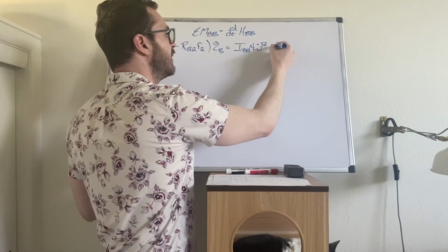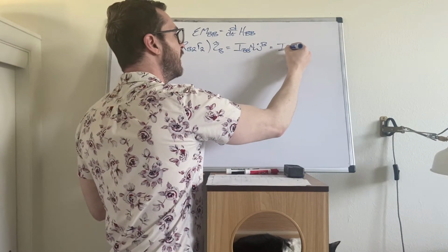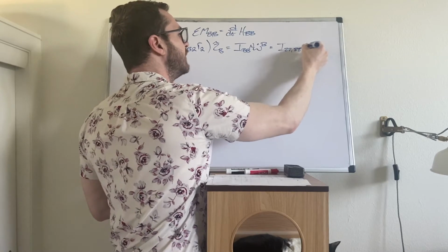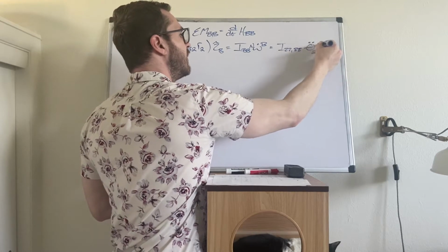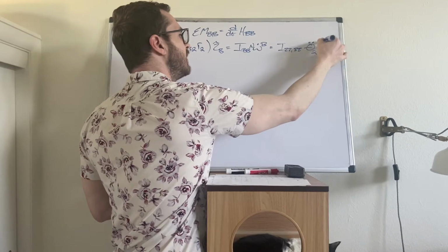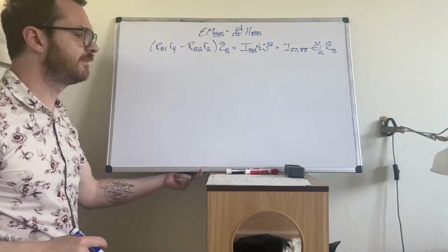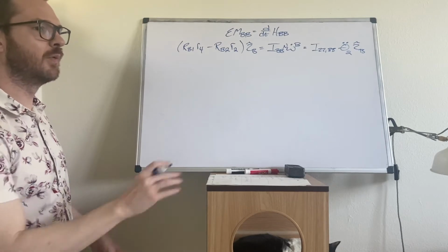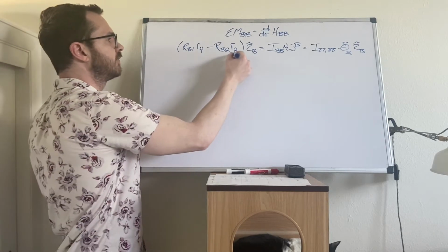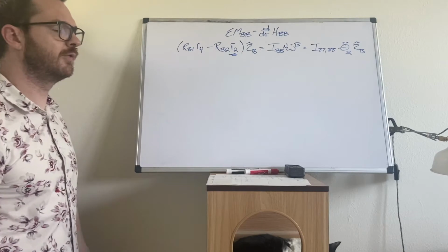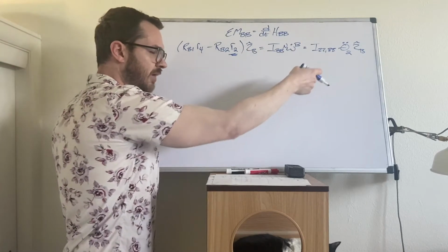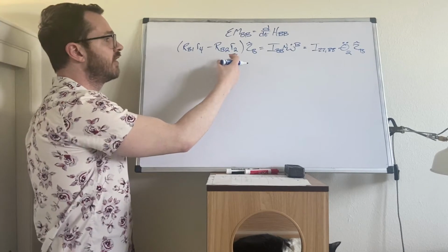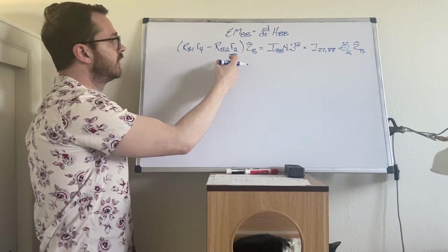So I_B, omega, and B. And the same assumptions that we did on body A lead us to I_ZZ,B and theta 2 double dot, and this is about the ZB axis. Okay, what was the point of us coming here? We wanted an expression for R2. Well, we can drop the ZB's, turn this into a scalar equation, and we can simply solve for R2.